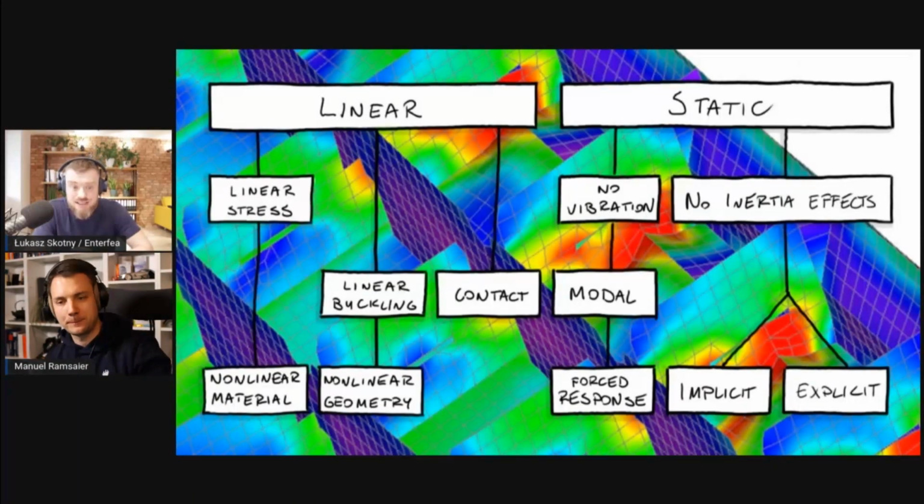And the real capacity, even for beams, would be like 2-3 times lower. Yeah. So you would be expecting a multiplier of 2, maybe 3, to be kind of happy. But what I've meant is that this works with beams because codes like Eurocodes and others, I'm sure as well, provide you with simple or relatively simple equations that allow you to take that into account.